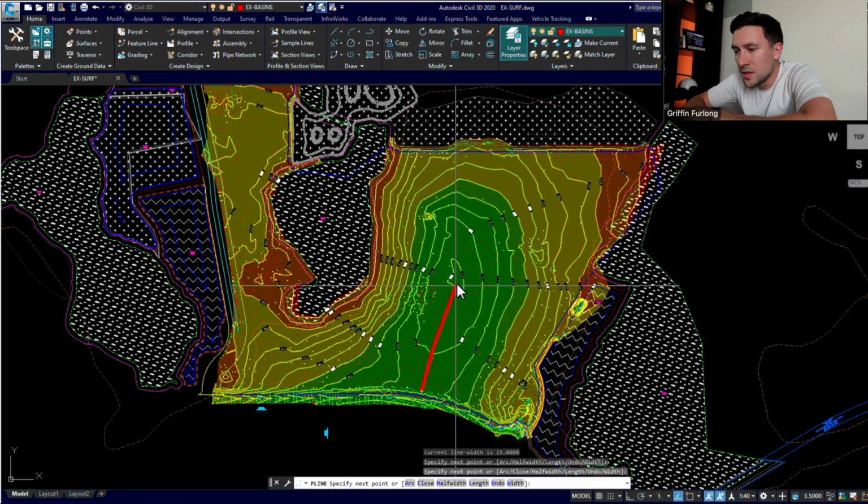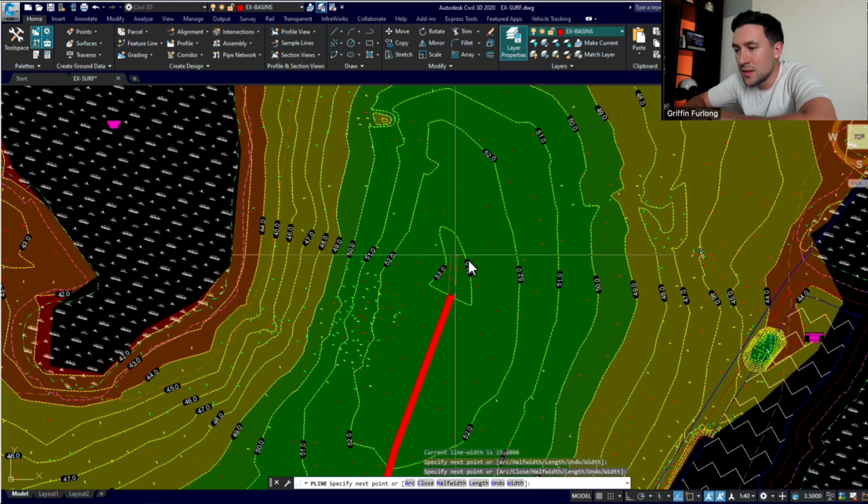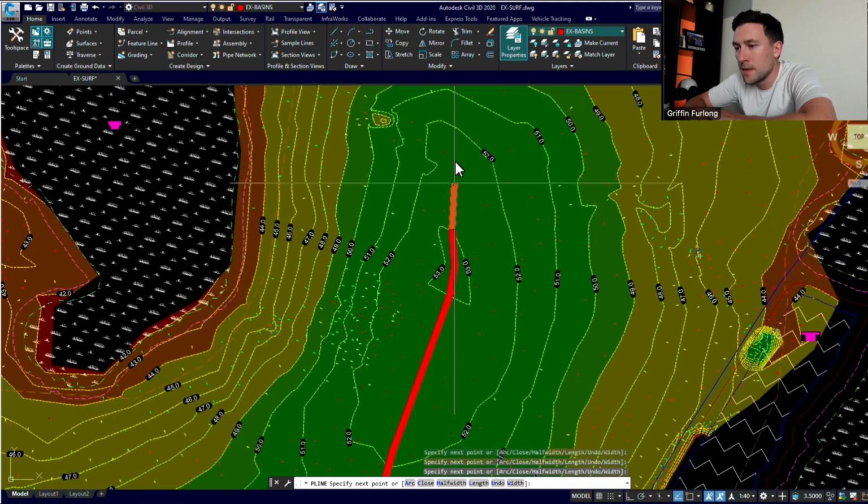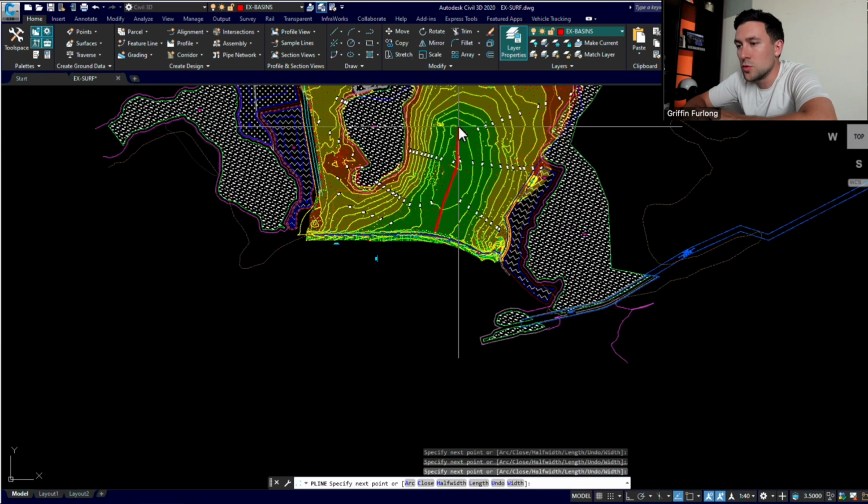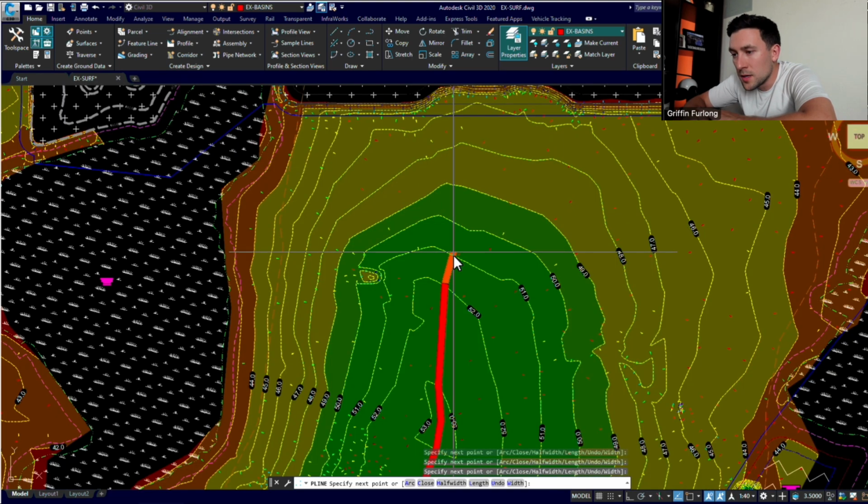So when we get to this point, I can tell that it is the very highest point. This is elevation 53. And I'm going to keep going across this ridge here. I'm going to try to do my best to go perpendicular to the contour lines. Zoom in. So again, it's very important that you take a perpendicular approach because that is the way that water wants to travel here. It's not going to be moving sideways. It's going to go perpendicular to these lines.